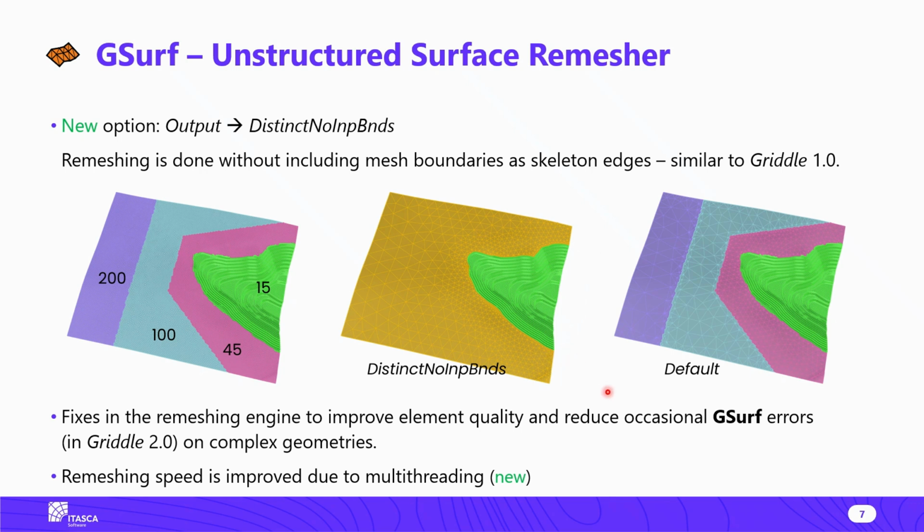This is a kind of unique way of remeshing, and this nice type of result can be achieved in other ways by specifying minimum and maximum edge size, proper gradation, and some other parameters. So there's really no necessity to roll back to using this approach, but for those people who like to use it, there's the option for you.